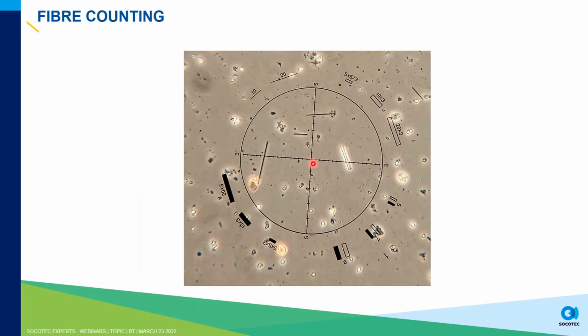So this was a slide taken on an asbestos removal project, removing amosite asbestos. We've also got this fibre on this side, this bright fluorescent fibre. It's probably not asbestos, but would need to be counted on that air test based on its size and dimensions. So here we have a slide with 5 fibres counted. The other thing to bear in mind is that all these specks you can see around this filter are bits of dust.